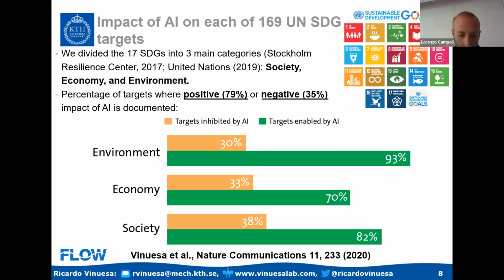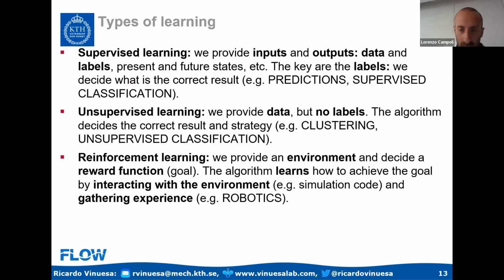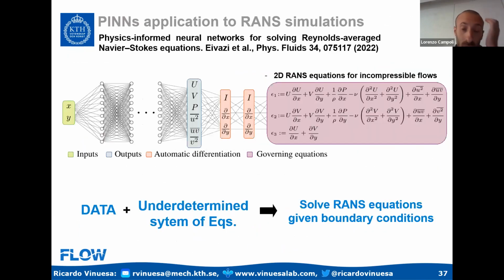Thank you. Another question is in slide 37, when you show the PINNs architecture, would there be any problem to extend the PINNs to 3D and to time varying problems? That's a very good question. So this PINN architecture is based on an MLP, on a multi-layered perceptron. So it's a very simple architecture. In 2D and steady is the most straightforward for this architecture. For 3D, it would be computationally much more complicated, but it could be done. I don't think that it would be very, very tricky to do it in 3D.